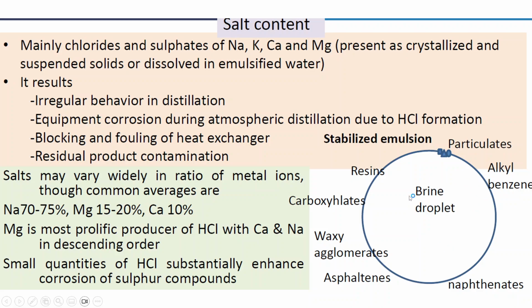So this is a brine droplet, that is basically salt dissolved in water. It is in the form of an emulsion in oil, surrounded by resins, carboxylates, waxy agglomerates, asphaltenes, naphthenates, and alkylbenzenes, which also co-stabilize this brine droplet.